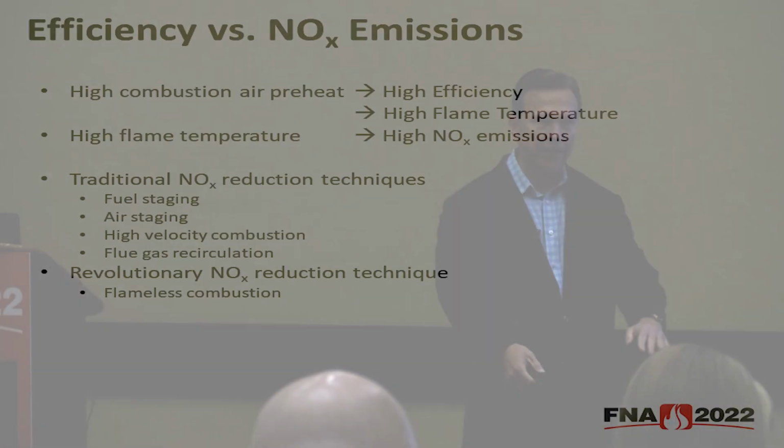And then you bring in the secondary air a little further downstream to complete the reaction and release some more heat. So you're spreading the heat out instead of concentrating it at one point. This helps to reduce the peak flame temperatures and thereby lowers NOx emissions.